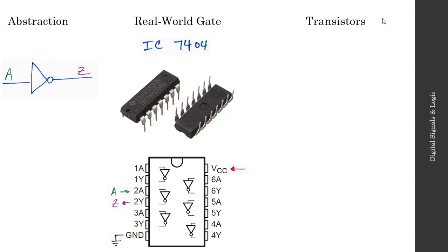And I could build this circuit on my own if I wanted to, something similar to what you may have encountered in 350, let's say, by grabbing a transistor from my part kit, attaching this to a power supply, and I could actually build my own logic gate if I wanted to here. So here's a quick schematic where you have VCC at top, you have maybe a 100 ohm resistor, let's say, you've got your NPN transistor, and by feeding a high or low signal in at A, you could monitor the output at Z to give you the inverted signal there.